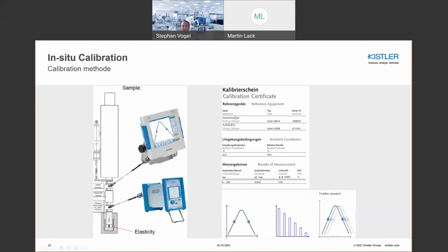And then, of course, there are some rules regarding the calibration sheet or test certificate sheet that you create. ISO 17025 has its own part with a whole description of what needs to be part of a calibration sheet. This is, of course, that you have the sensors and equipment identified by a serial number, for example, but it also includes, for example, the uncertainty for each calibration point, for each measurement point.